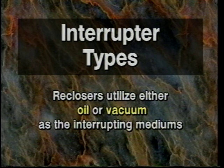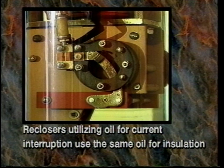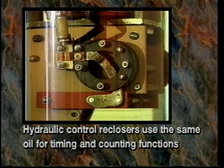Interrupter types. Reclosers utilize either oil or vacuum as the interrupting mediums. Oil interruption is utilized on most single-phase reclosers and some three-phase reclosers. Reclosers utilizing oil for current interruption use the same oil for basic insulation. Most reclosers with hydraulic control also use the same oil for timing and counting functions.